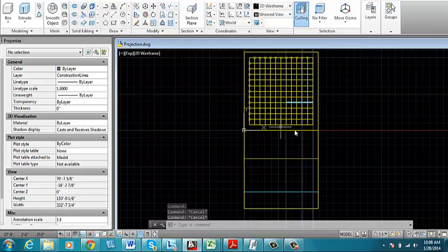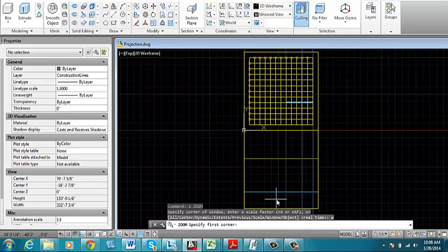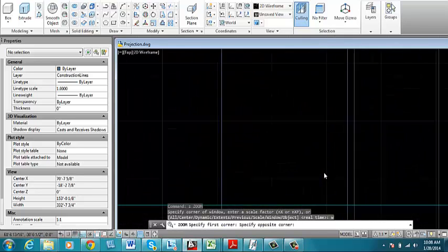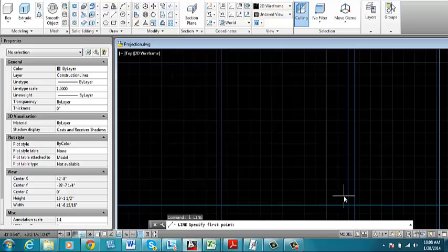All right, now these two walls that I have here, there's one that's located right here, and that one is 3 feet. And there's one here, and I'm going to make that one 9 feet. So in elevation, I'll zoom in a little closer here. I would simply begin from this point right here, begin making a line that's 3 feet, press enter.